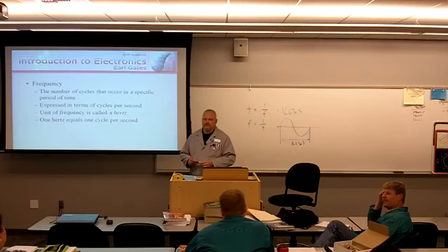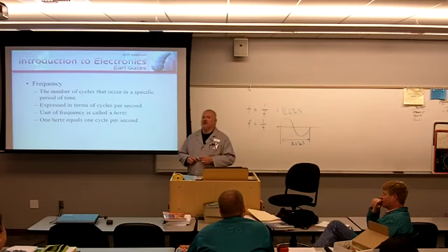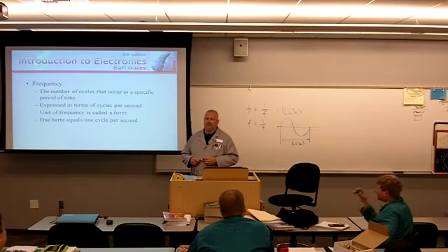So if you divide that by 2, which gives you about 8.3 milliseconds, that means that the lights are turning on and off every 8.3 milliseconds, right? When it goes from the positive to the negative, technically, but we just can't pick it up. And in Europe, it's 50 hertz, so that period of time is even more pronounced. But for an incandescent bulb, the filament doesn't cool down enough to notice for some of these bulbs, and some people don't dig it.